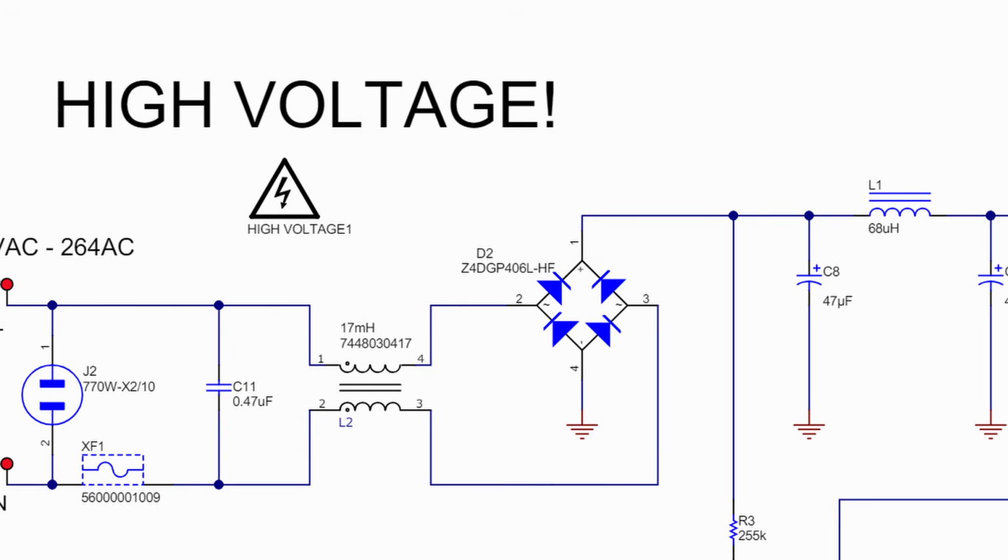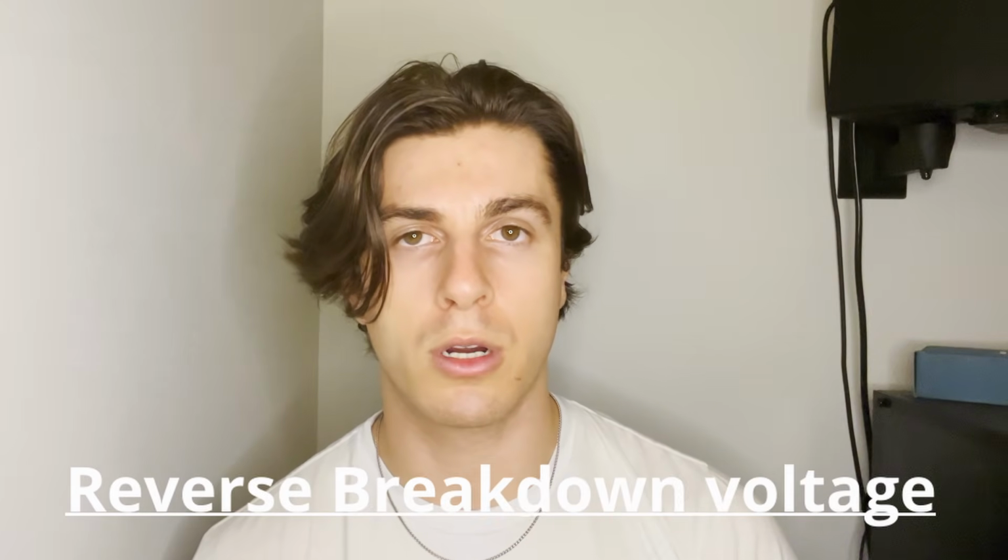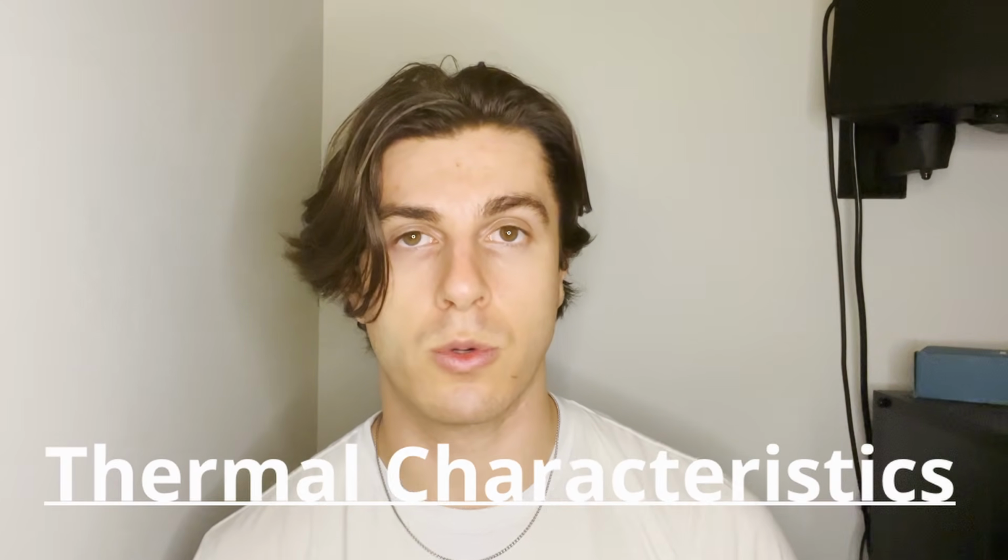Oh, and before we go on to the theory of operations section, there's another component that I want to mention that is not shown on the power stage for the flyback converter, and that is going to be your full wave bridge rectifier. And that component goes before your input capacitor, and its job is to rectify your AC input signal into a DC signal. So whenever you're selecting the component or components for your input bridge rectifier, you want to be familiar with parameters such as your reverse breakdown voltage, your current rating, power dissipation rating, and the thermal characteristics.